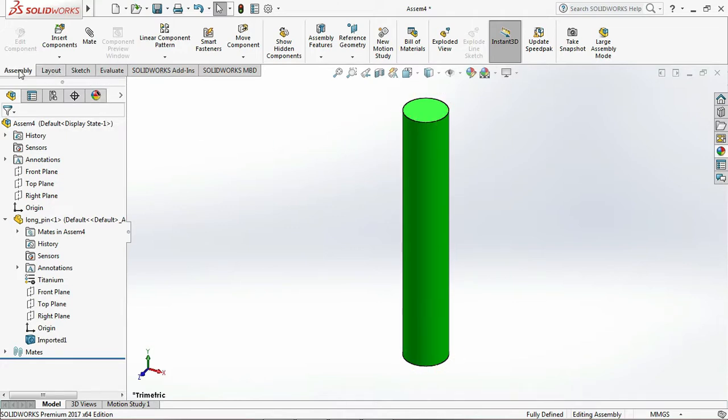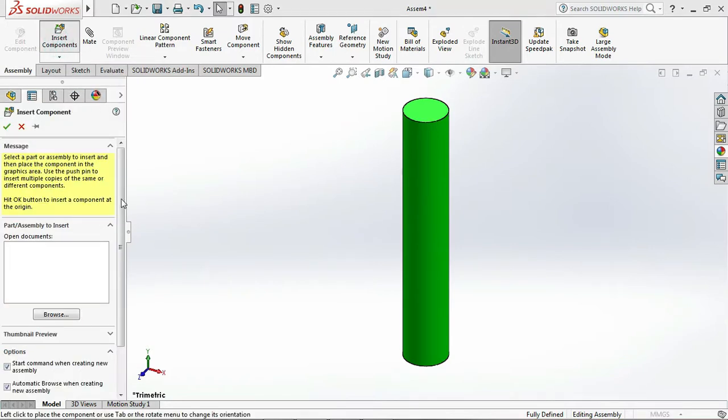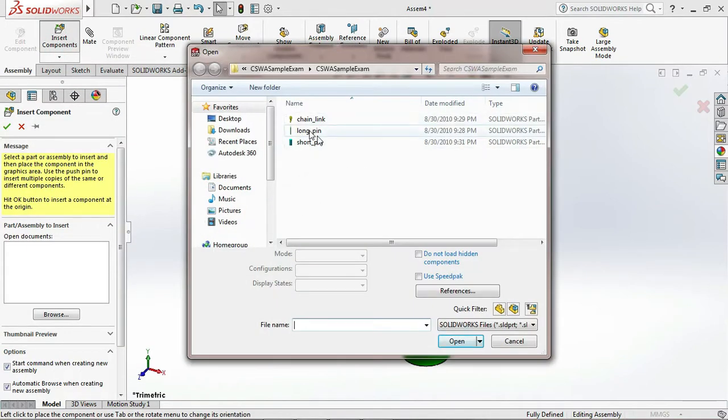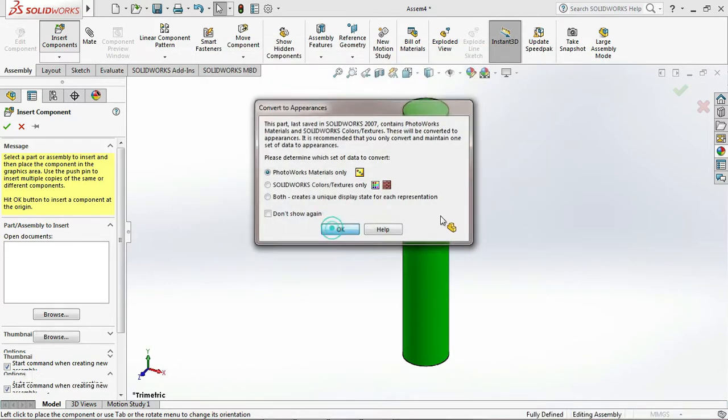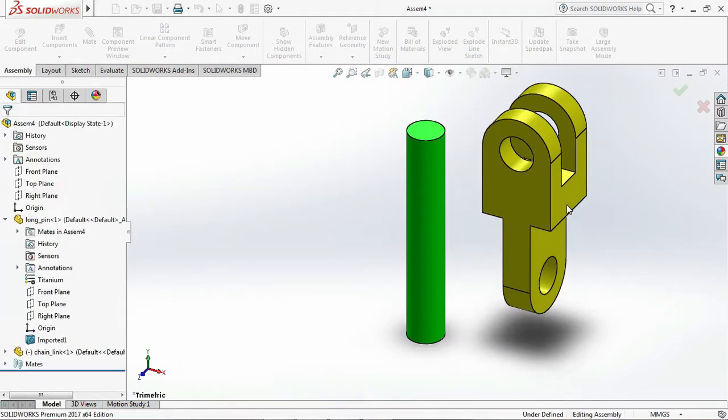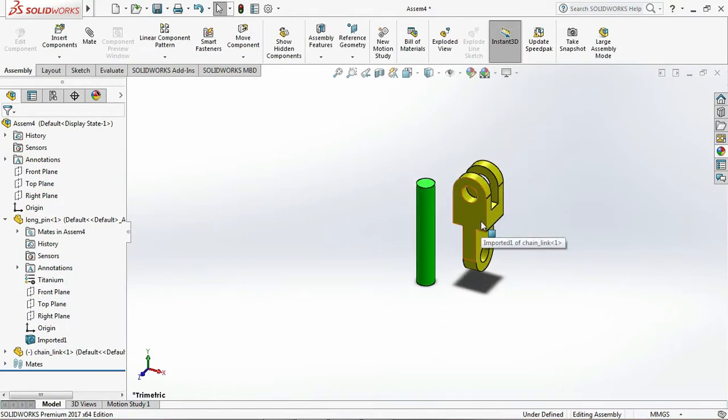So the other step followed is browsing the component, and then I choose the chain link and then I browse the chain link. I just want 4 components of the chain link. So what I'm going to do, just click Control on your computer keyboard, then hold on the Control and then drag.